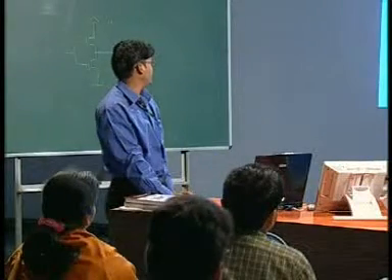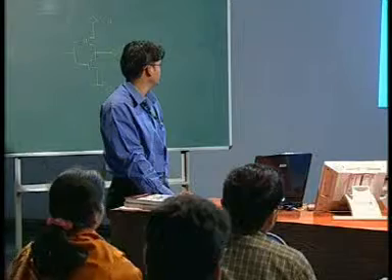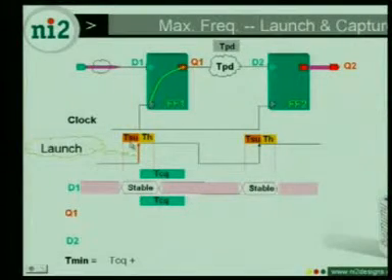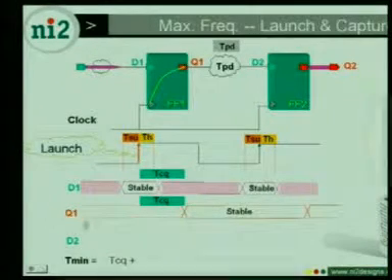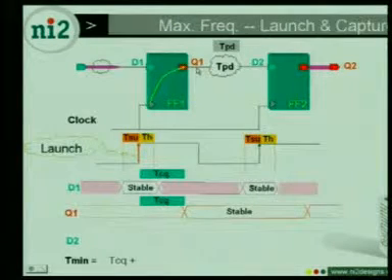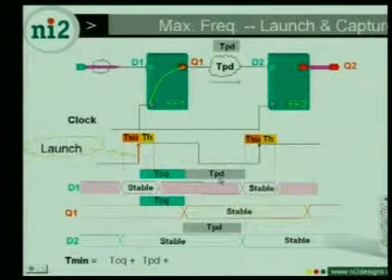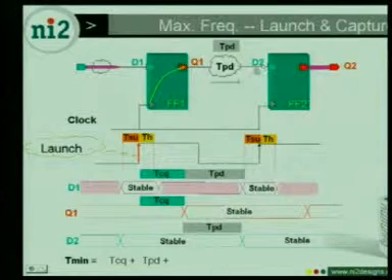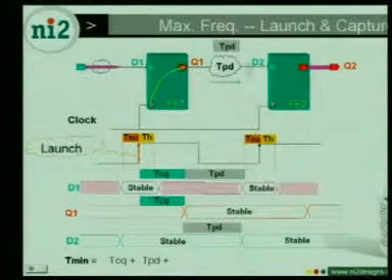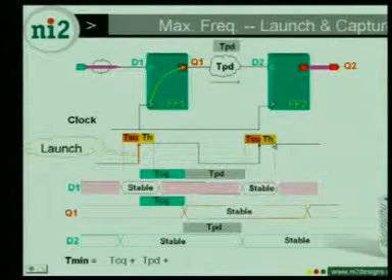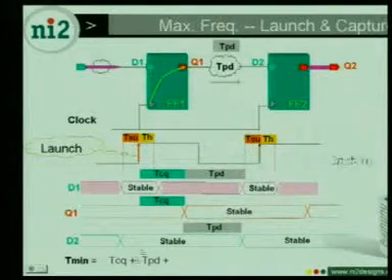See this, when the data will be stable here at D1, after TSU, the setup time, my data will be out here at Q, that will be TCQ, the clock to Q delay. So I will add that: T minimum will be T clock plus, then next, you can check that now my data is stable at output of Q1. After some delay, this TPD, I will get this at this D2 point, and for this the setup time will be this and hold time will be TH.